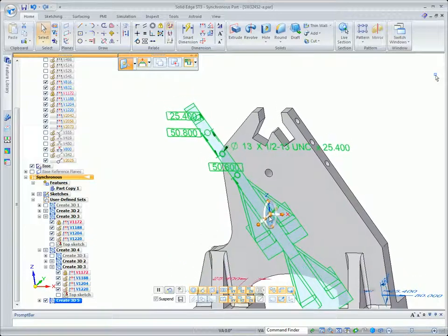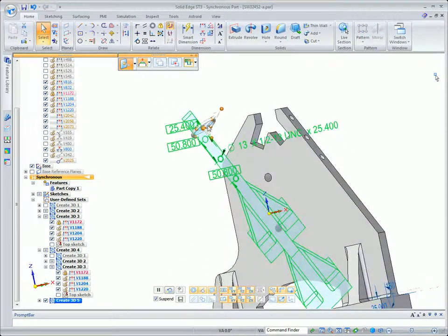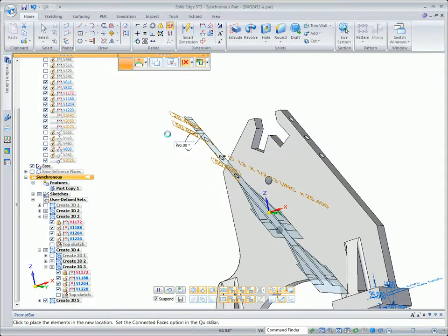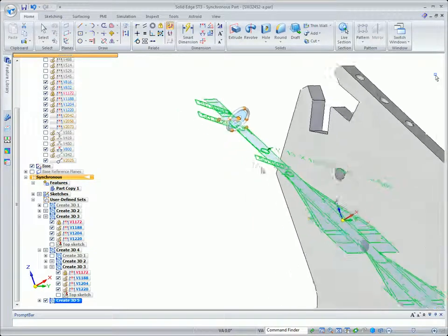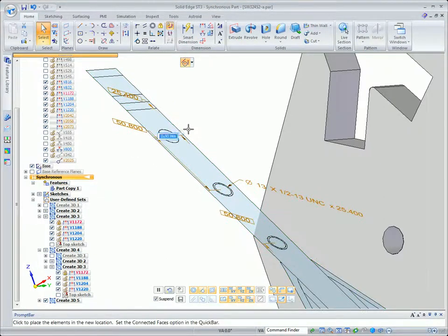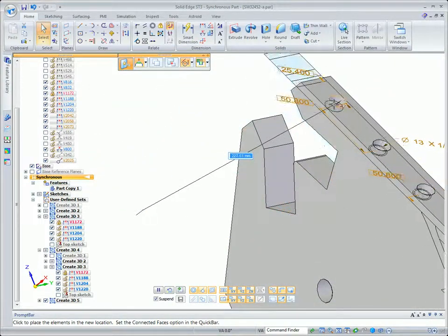Now what I want to do is actually manipulate that to get it in the correct orientation, because it brings it in relative to its origin. Rotate it 90 degrees. And then I need to change the orientation of the steering wheel, because what I want to do is put that steering wheel centered on a hole and then use that to align to a hole in our model.